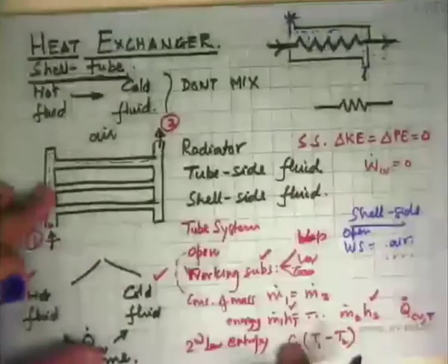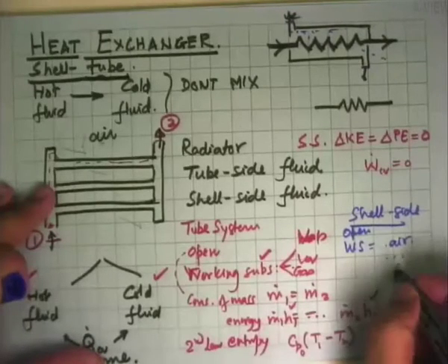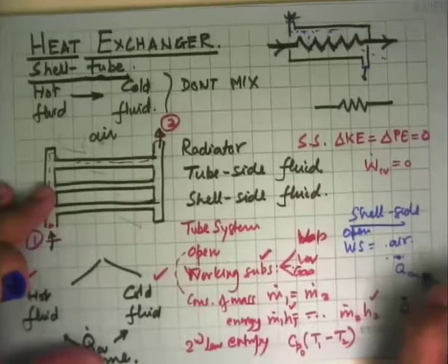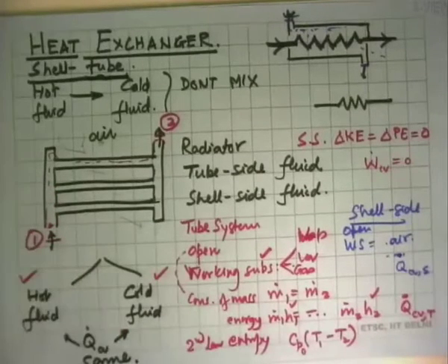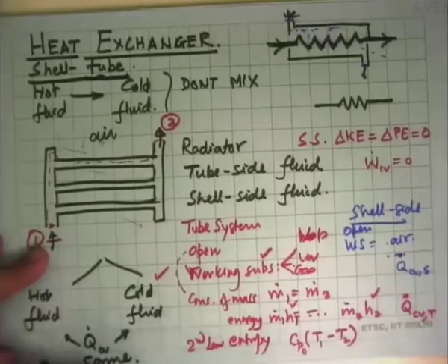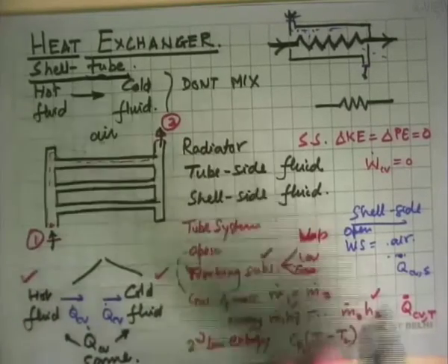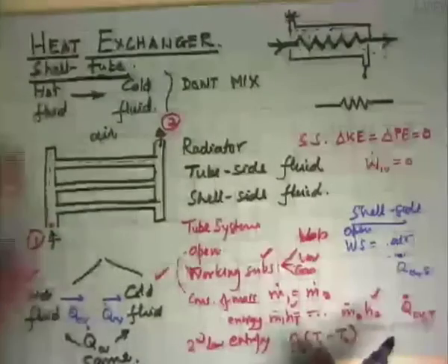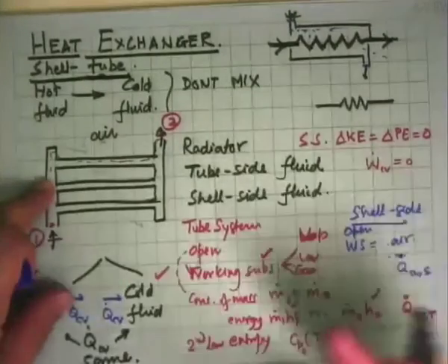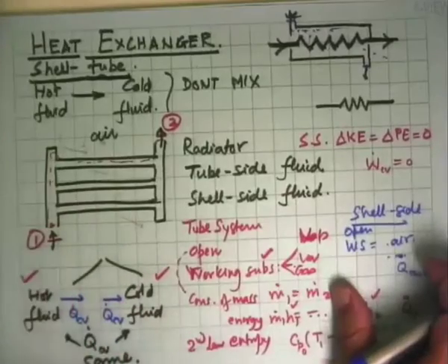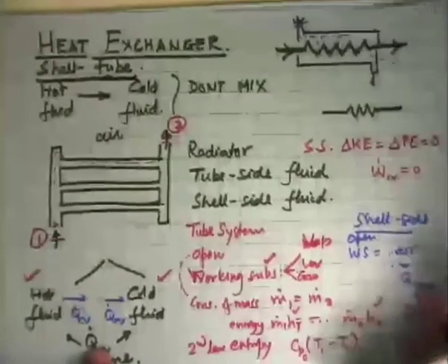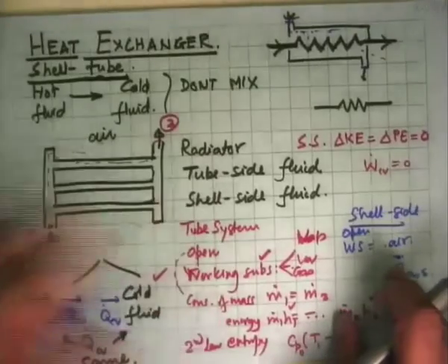And then we follow exactly the same process that we did here, get the properties, and in this case we will get Q dot CV for the shell side. And the thing that joins and completes the problem is that these two terms have to be equal, that is, heat given out by the hot fluid Q dot CV is heat transferred to the cold fluid, and these two are equal. So something that we know from experience, that m dot Cp T1 minus T2 for one substance will be equal to m dot Cp T1 minus T2 for the other substance. That comes out from this derivation.